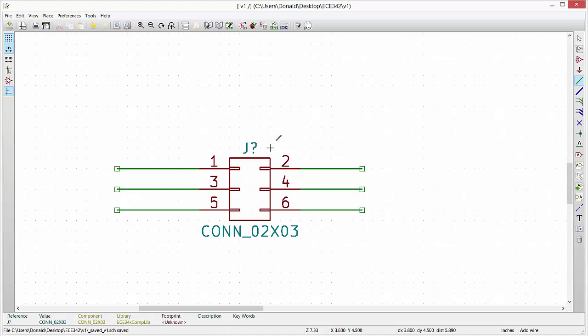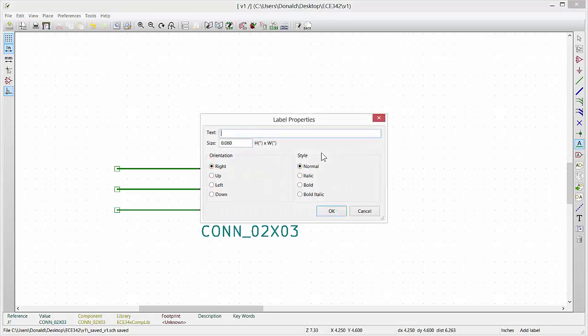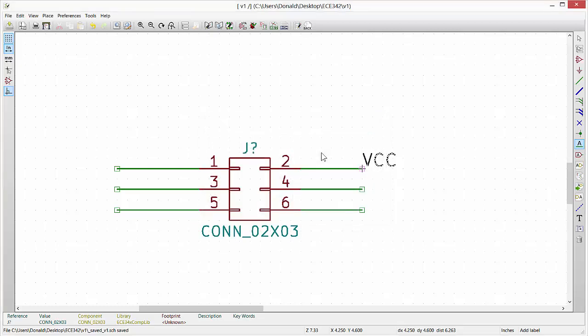This pattern of 6 is exactly as stated in this diagram. But we need to implement it so that we're able to program our chip. To do that, I'm just going to connect it to the proper pins. And again, remember that as long as I'm doing a net name, this system will connect these things for me.